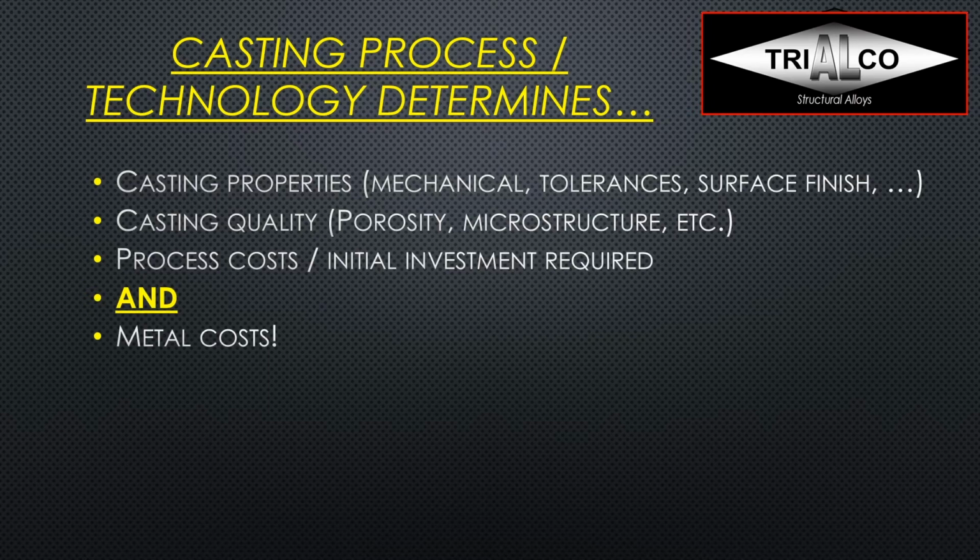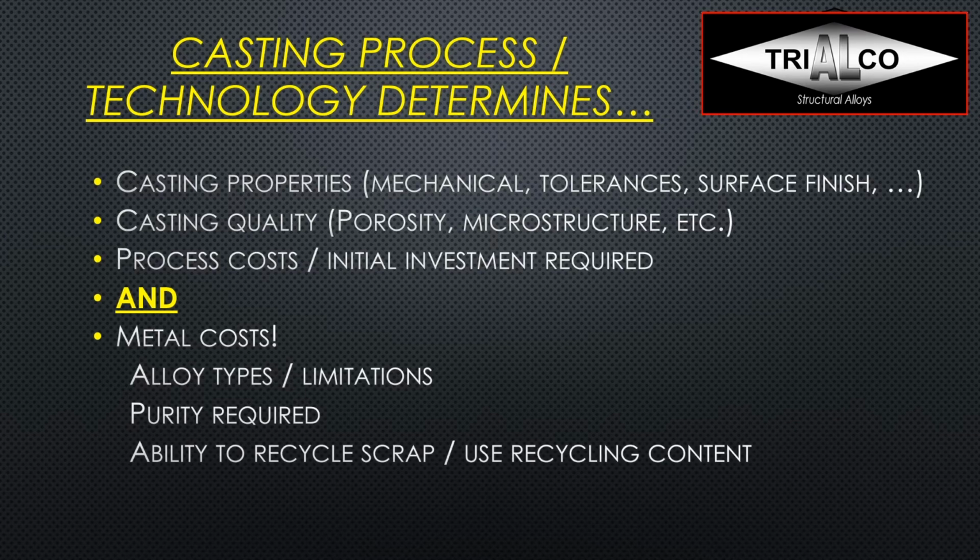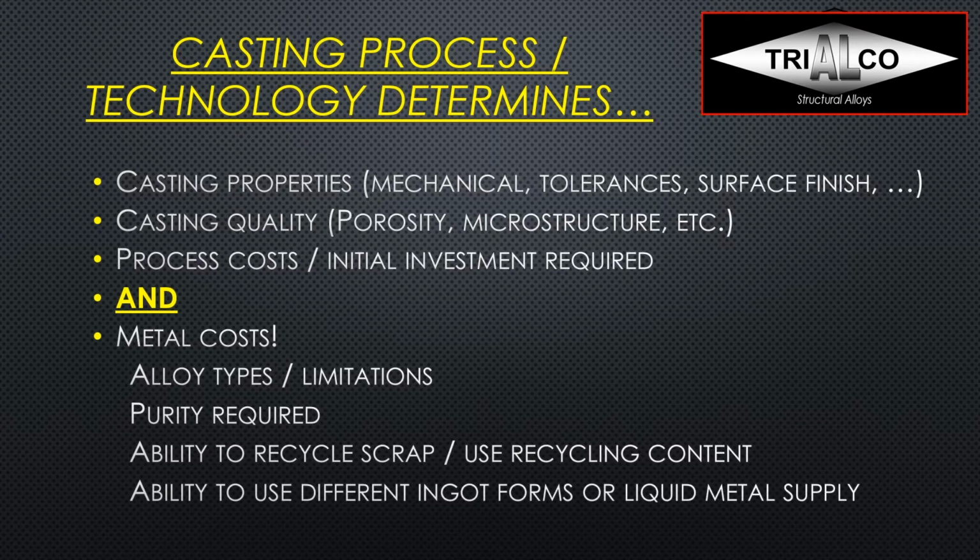And of course, metal costs, very important. It will determine the alloy types and limitations that I can use for this process, the required purity that I will need, and the ability, therefore, to recycle scrap internally or use recycling content in the alloy that I'm getting, and the ability to use different ingot forms or even liquid metal supply.